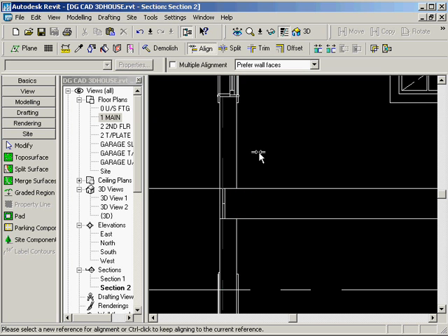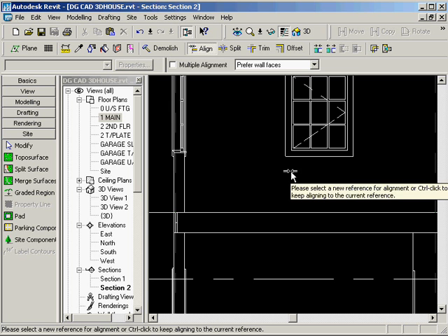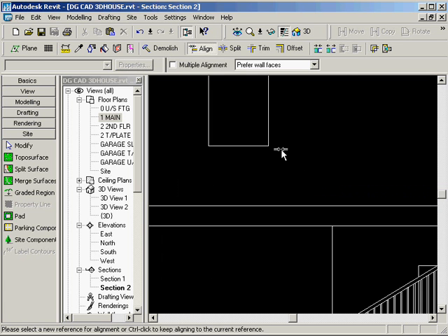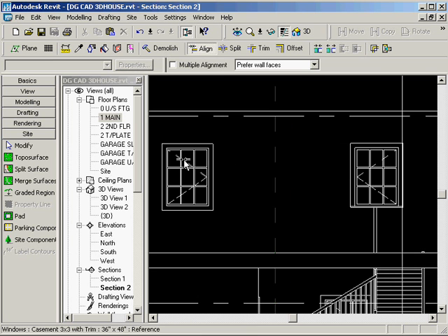That starts to come in pretty handy when you've got structural walls that are all above each other. You're going to want to go in and cut little sections everywhere, basically, and really get to know how to use this align and locking tool, because it can really help you out in a lot of ways. For horizontal alignment and vertical alignment, you can go into any cross section.